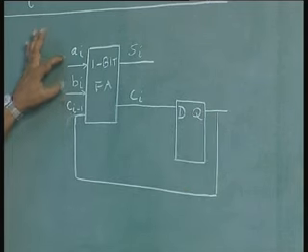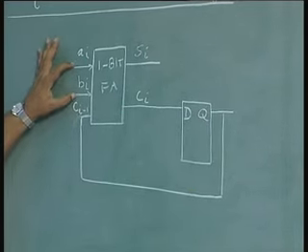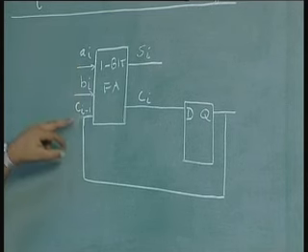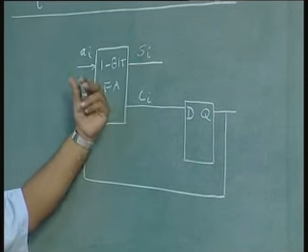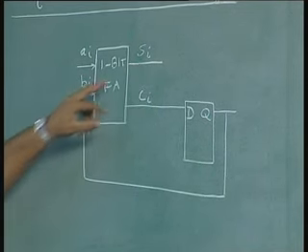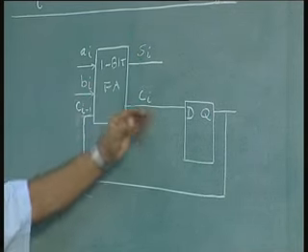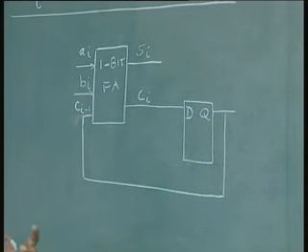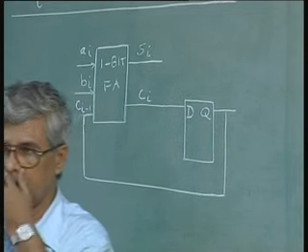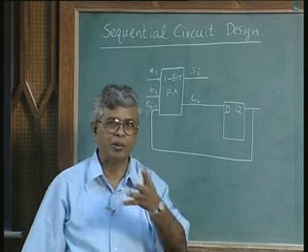Second bits, A1 and B1, come. At that time Ci minus 1 will be there, in this case 1 or 0 depending on the previous bits. A1, B1 get added, generating a new Si and a new Ci, that gets stored, and so forth, and it can go on. So, the hardware does not restrict the number of bits to be added.